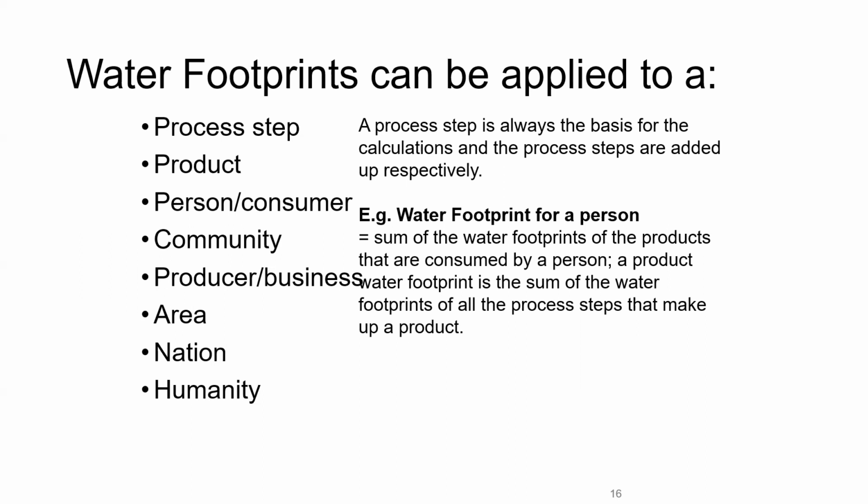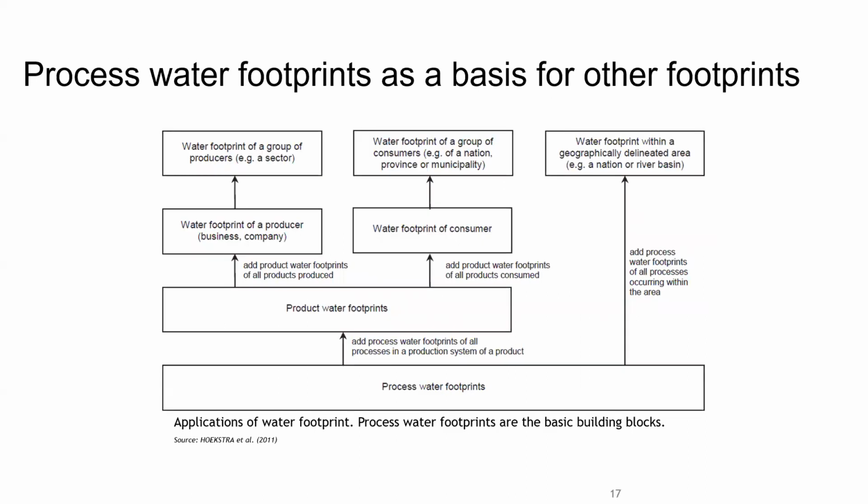So whenever you are calculating the footprint, you have to write the direct water footprint and the indirect water footprint. Whatever direct consumption by the industry that you are calculating on a daily or annual basis is known as direct water footprint. But what about those raw materials which have already been processed somewhere else? Whatever raw material you are using can be produced at some other place by some industry as a product, right? Now you are transporting those products as raw material for your company. Now you are producing another product from those raw materials, and you are calculating the water footprint which has been directly consumed by your industry. So that is the direct water footprint.